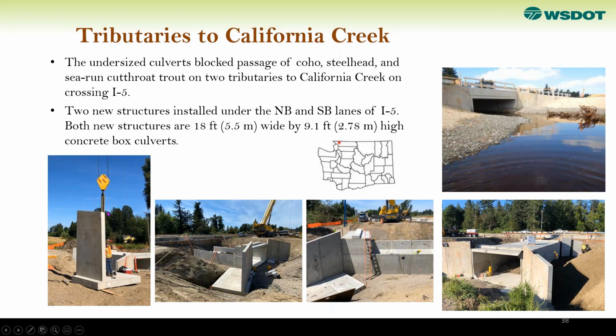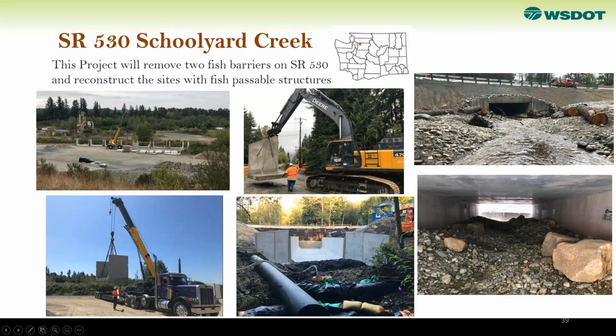So we can see here a precast wing wall, and then the precast footing being installed, and then a split box that is put together, including the precast head wall and so on. So everything in this job was precast. It was done in a very short period of time to meet the accelerated bridge requirement.